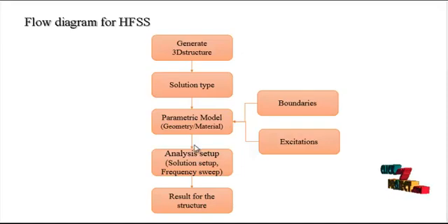In the analysis setup, we give a start and stop frequency, and then the center frequency at which the antenna will be designed, for example 3.5 GHz. Finally we calculate the results of the structure. The next step is the proposed design of the antenna, which is shown in the view.